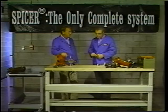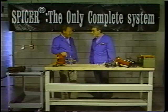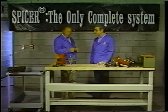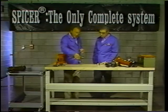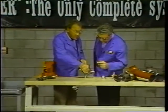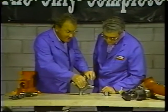Boy, these components sure look different from the ones we just saw. Well, that's for sure. These component failures were all caused by one of the three items I mentioned before. Let's take a look at this U-joint first. Okay. I see that the trunnions on this joint look like they've been worn pretty badly. Well, they have. That's called spalling.